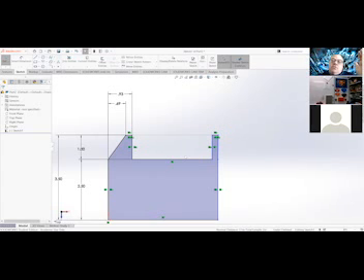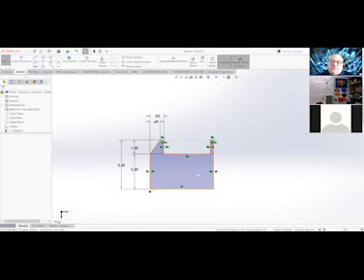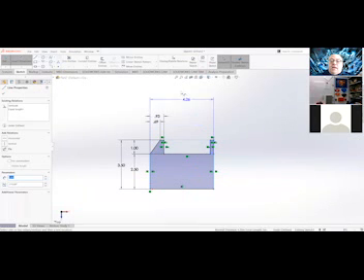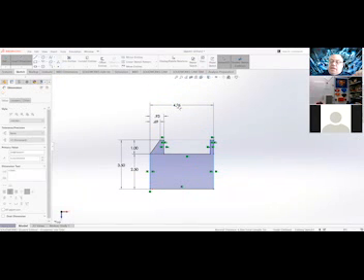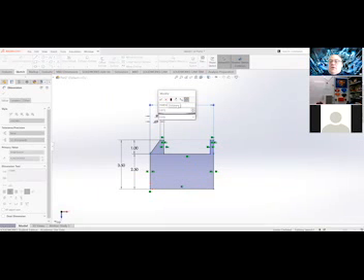Well, one thing is I haven't set the width of my object yet, and so I want to be able to do that. So that's our next thing, the overall width of my part. Let's see if I remember that. That was 2.875 is the width. So smart dimension, left line, right line, bring that up above, 2.875. That's what we're going to type in there. Oh, we hit enter, excuse me.